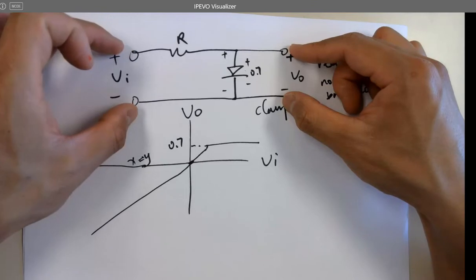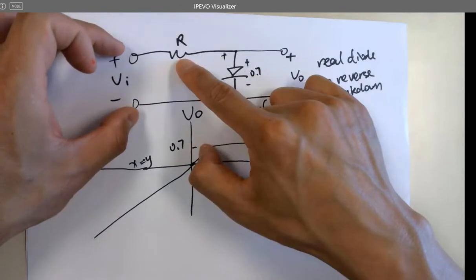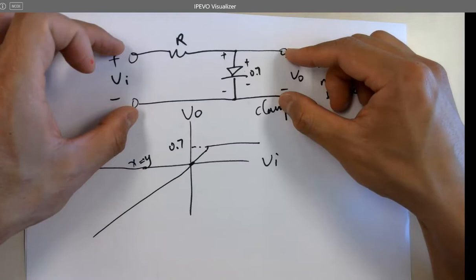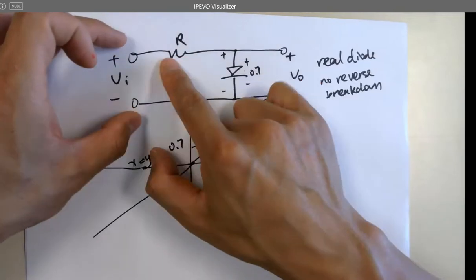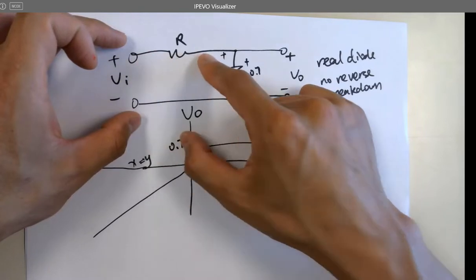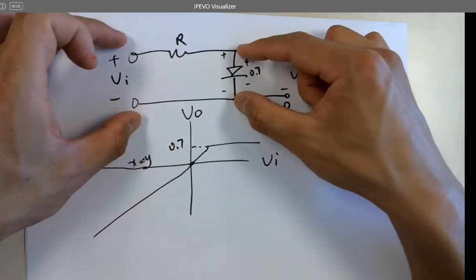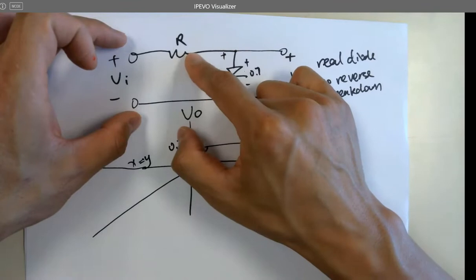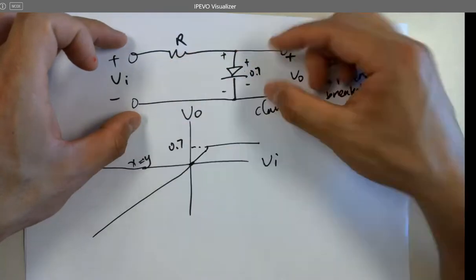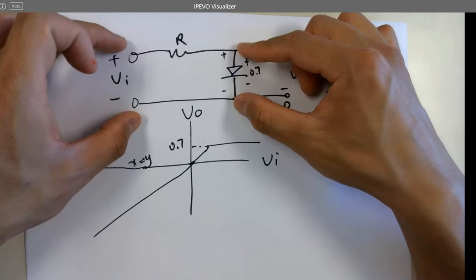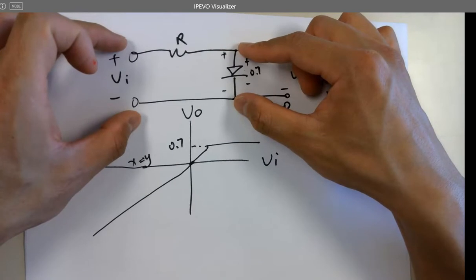Where are these voltages? They're being lost somewhere, right? Where? Yeah, the resistor. Voltage is dropping, more voltage. Whenever you increase the VI, it's just injecting more current into the circuit, even though this one stays at 0.7 volts, but more current flows through the same resistor, just more voltage drop. But still dropped to 0.7 volts. Would you break the diode if you didn't have the resistor in? Yeah, it's being broken really quickly.